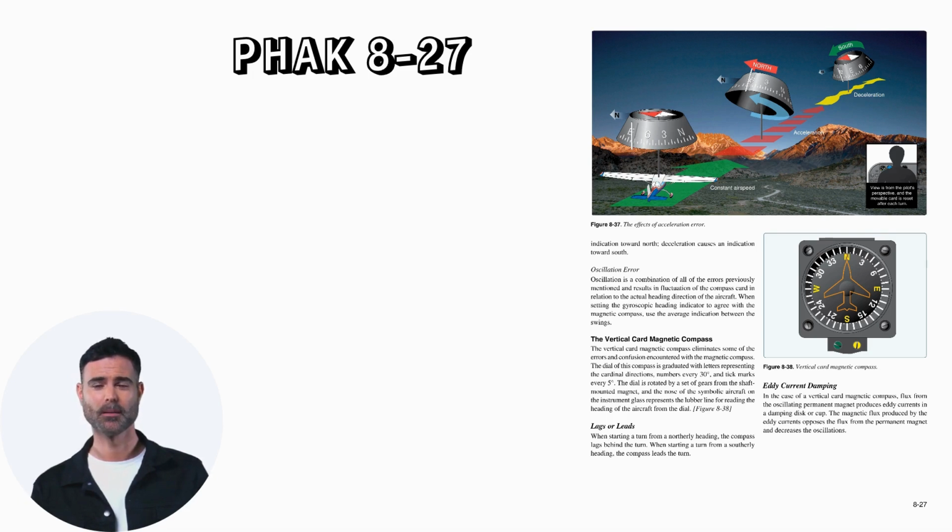The vertical card magnetic compass. The vertical card magnetic compass eliminates some of the errors and confusion encountered with the magnetic compass. The dial of this compass is graduated with letters representing the cardinal directions, numbers every 30 degrees, and tick marks every 5 degrees. The dial is rotated by a set of gears from the shaft-mounted magnet, and the nose of the symbolic aircraft on the instrument glass represents the lubber line for reading the heading of the aircraft from the dial. Lags or leads.